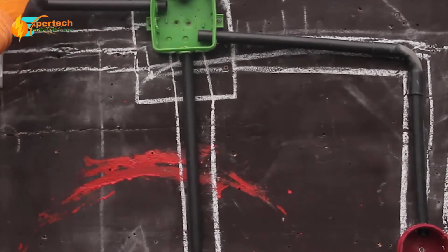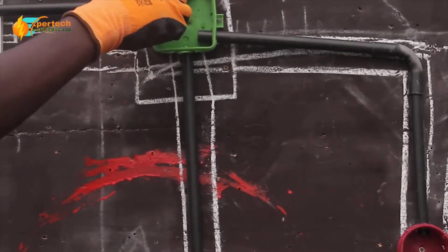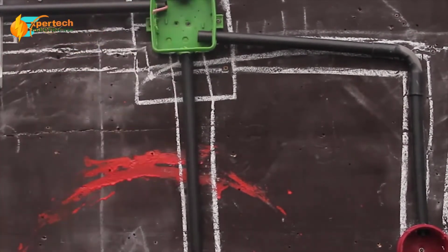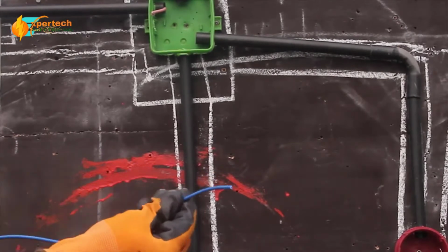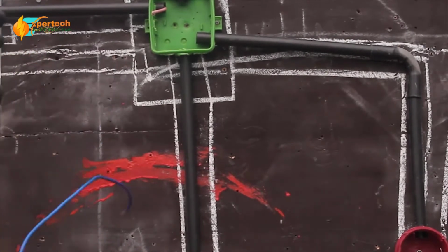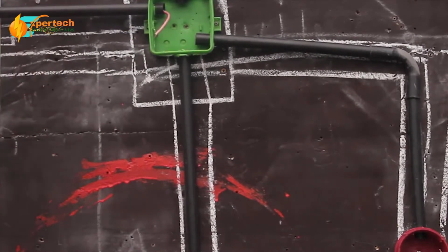That blue wire stands for the phase conductor, which is connected to the one-way switch terminal through the fuse of 6 to 10 amps. The neutral is connected directly to the lamp. When the switch is closed, the conductor is switched on.